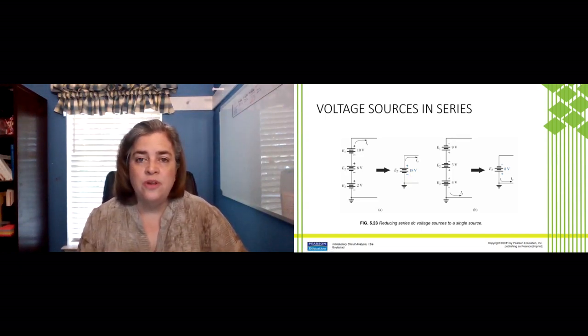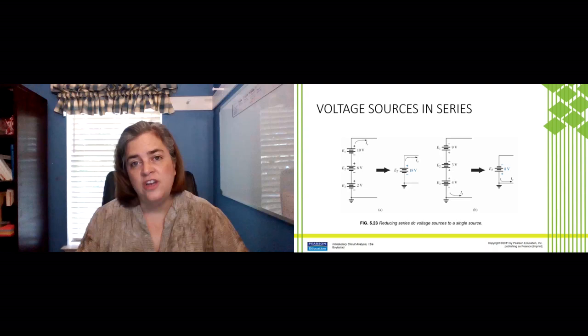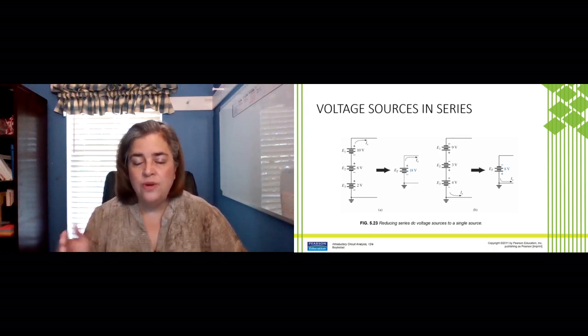In a typical circuit where you might put 4 double A's, they would be lined up just like this, all in the same direction. When you have 4 double A's and each is 1.5 volts, you would be applying 6 volts to your calculator circuit.